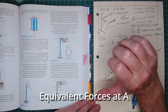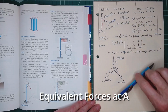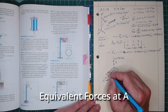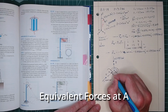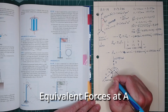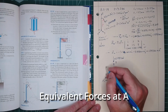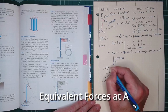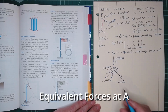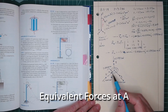So a positive moment is going to be going this way, but we have a negative moment, so it's going to be going this way. So I'm going to draw this on here. So it's going to be drawn on here like this. So about that axis, we're going to have a negative moment, or a moment in the negative direction, and that's going to be 7.496 kilonewton meters on there. So we have that moment acting about our x-axis.